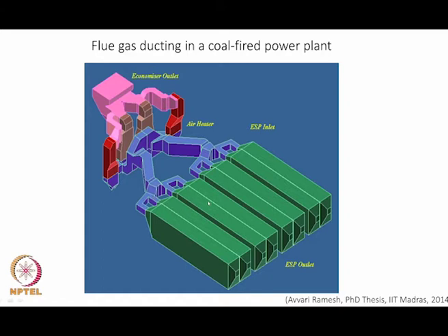And when we are looking at a thermal power plant, it has to be operational continuously, but we also need to look at the maintenance issue. So, that is why we need to have duplication. So, the 2 are duplicated here so that you have 4 of these, and then you have an arrangement here with a gate valve. If all the 4 are working, then 2 of them will be taking the load here and 2 of them will be taking the air here.